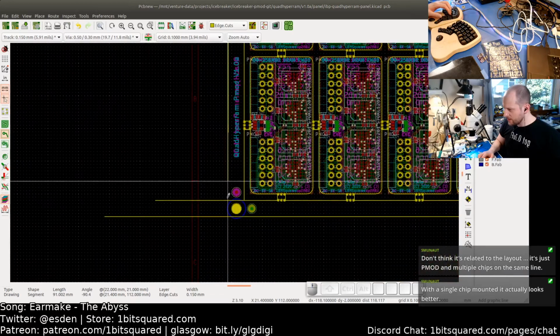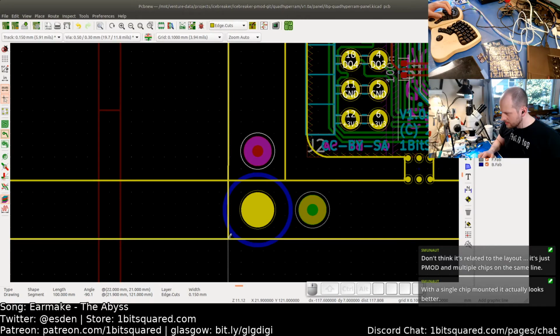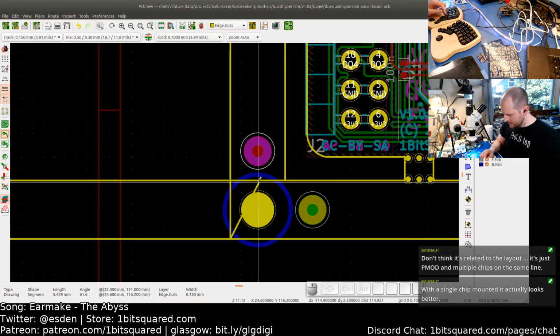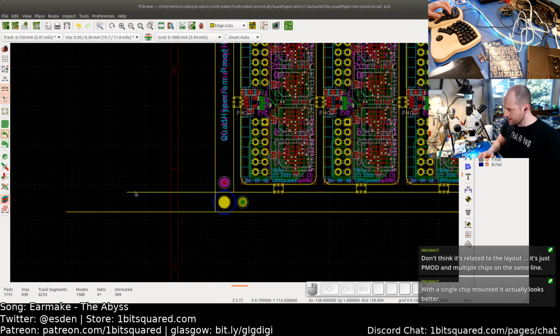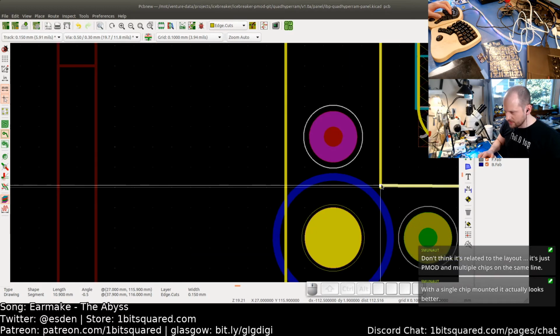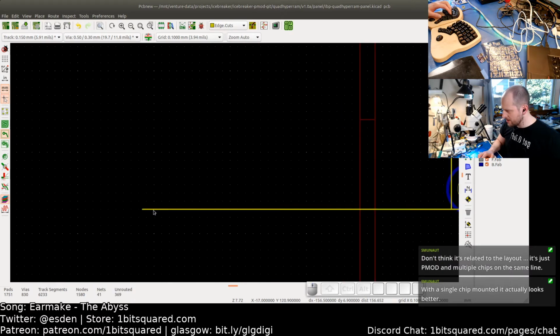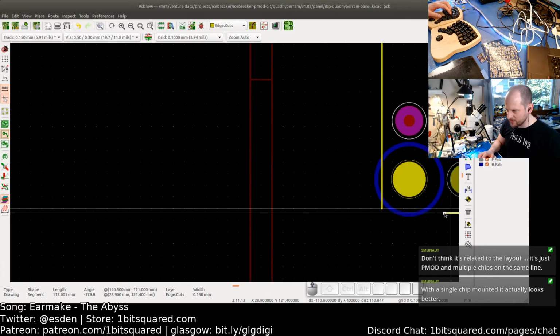The cool thing is that after we are done with cleaning this up, we can verify if we did a good job by just running the 3D renderer in KiCad. It will complain if any of the board outlines have issues.